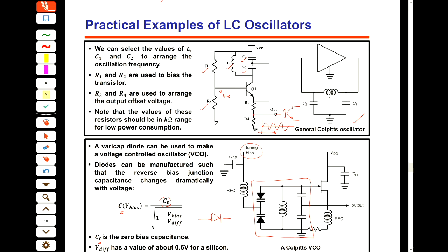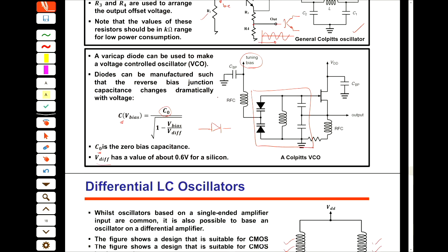I mean, you design your oscillator for L, C1, and C2, but then your C2 is in parallel with the C input of the next stage, and then it changes. So to avoid that, we put a buffer and then design. And when our design is completed, adding any circuit at the output of that buffer doesn't change it anymore.